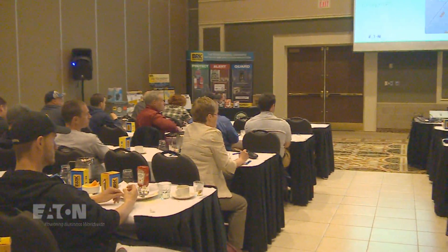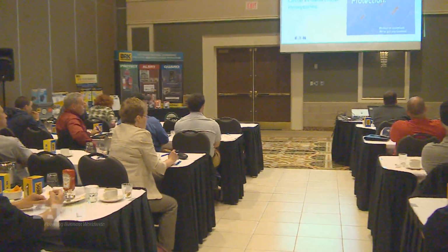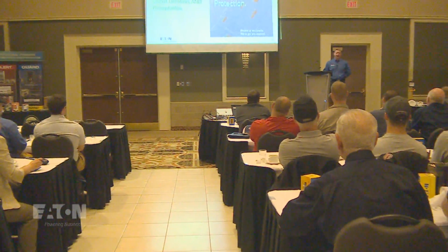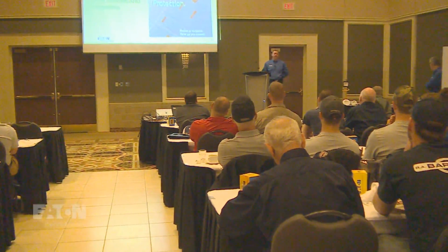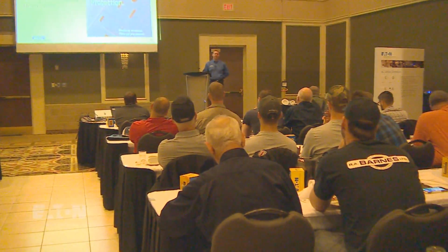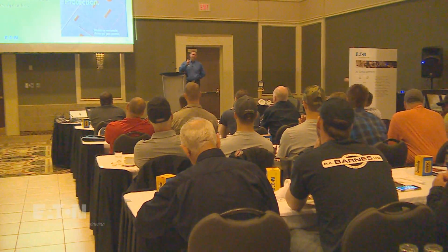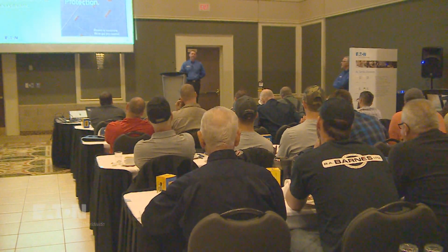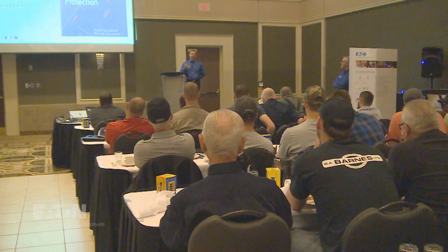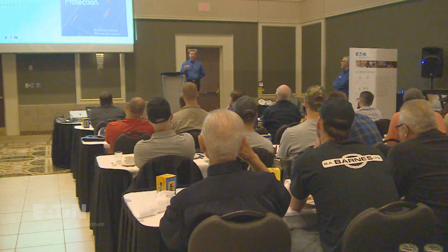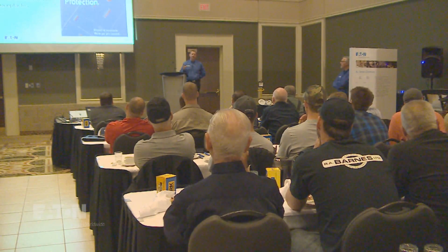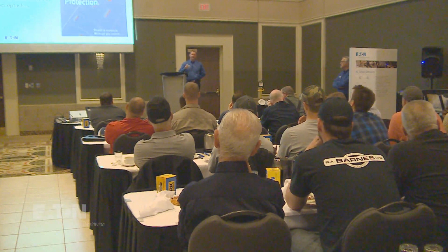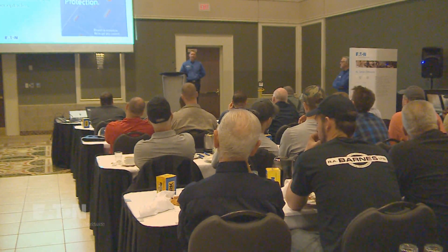So the question is, what's the difference between the arc signature for something like a light switch or a vacuum motor starting and the actual arc faults? The actual answer is there's not a lot of difference. But what the breakers are trained to do is that one arc when something is turning on, or a couple within those milliseconds, is acceptable. If it sees 4 or 5 in a row that exceed that time limit, then it goes, hey, maybe now there's a problem. So even though the arc signature is very similar, it's looking for the typical cycle of turning on and off and starting.